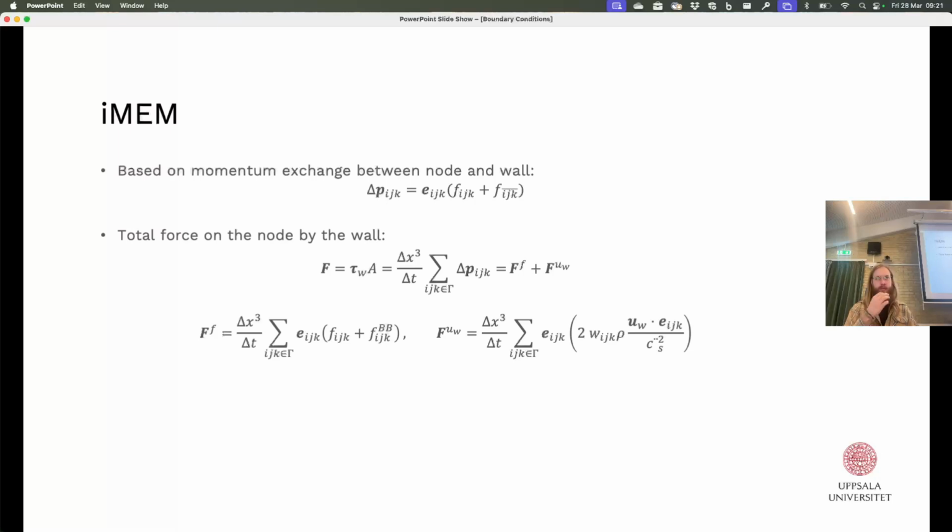I think the nice thing with this really is that what you definitely see from outside, if you just look at the very, very big picture, is the momentum exchange between the fluid and the solid. So this is unquestionable. And now you actually know what momentum is flowing into the wall, and you just adjust the momentum that is flowing out of the wall such that you get this particular thing. So once you know what friction you have, so how much momentum you want to exchange, then this becomes very, very simple.